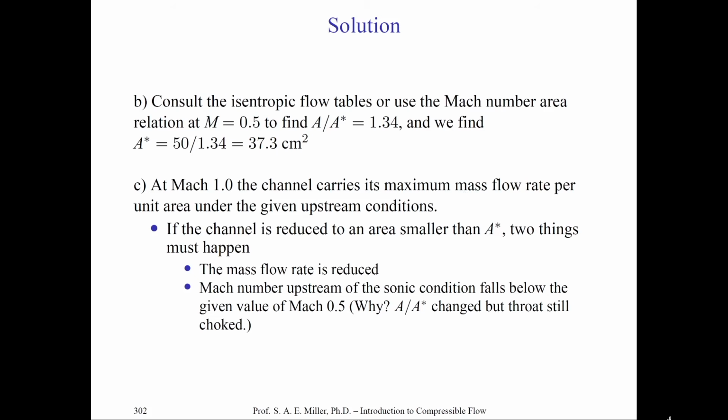If your area increased, you know that this, of course, is unphysical because we're in a subsonic flow, and we would decelerate the flow, of course, to get to this equivalent area ratio, which wouldn't make any sense. It's unphysical. So be careful of that. If you find A sup star to be larger than A in a particular problem, you know you've made a mistake.